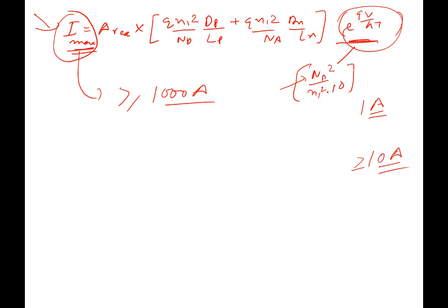You would try to make the junction higher and higher doping. So you would try to increase ND, and this is another thing, if time permits, we'll see that. As you increase ND, another parameter called breakdown voltage starts going down. So as you try to make Imax higher by increasing ND, your breakdown voltage starts to go down.